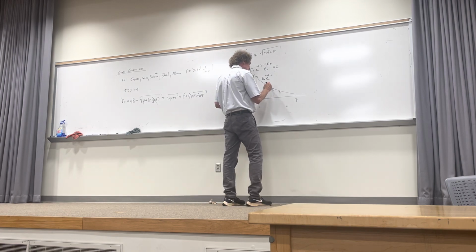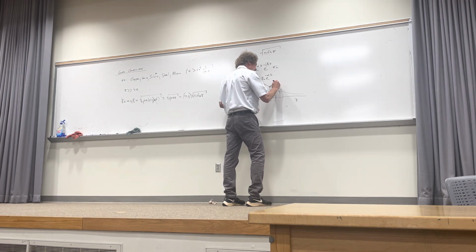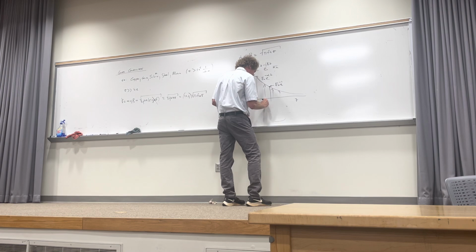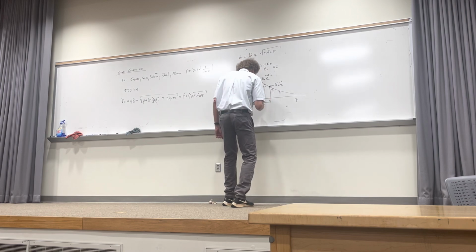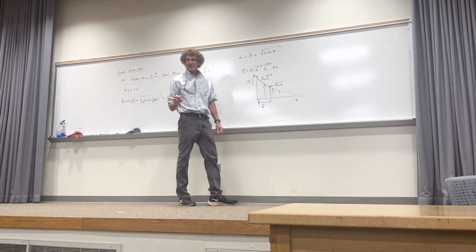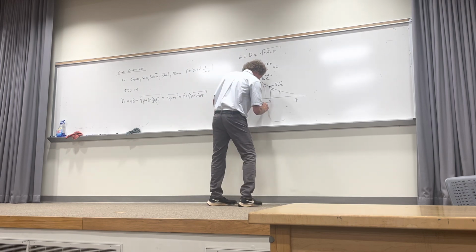But here's something that we use all the time. We say the point where you have the E field being equal to E naught e to the minus 1, at this point, is given the symbol, unfortunately the same symbol as the loss tangent, gamma, and this is called the skin depth.